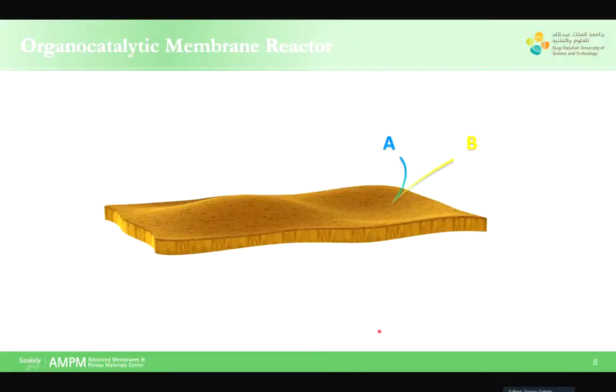So the first research I'd like to talk about is organocatalytic membrane reactors. The idea is to do reaction, catalysis in this case, and separation at the same time. So imagine that you have a membrane with a given pore size, so you can do size exclusion separation, and at the same time this membrane acts as a catalyst to perform a given reaction.